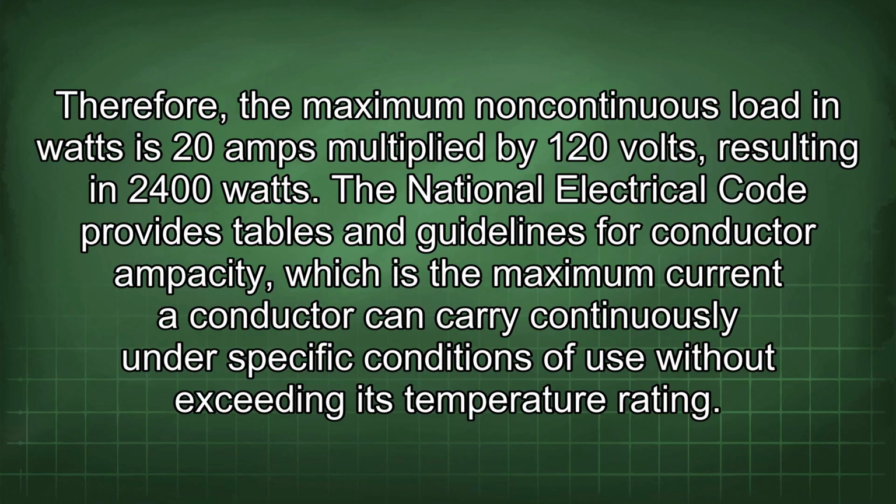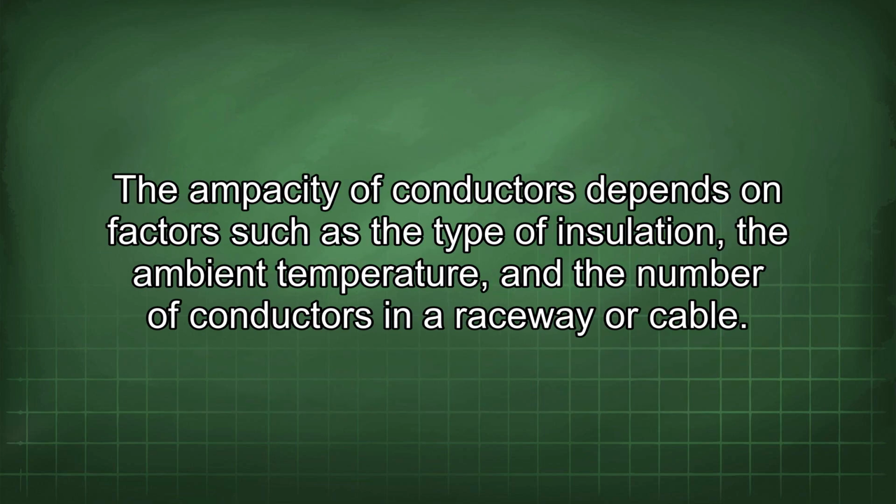The National Electrical Code provides tables and guidelines for conductor ampacity, which is the maximum current a conductor can carry continuously under specific conditions of use without exceeding its temperature rating. The ampacity of conductors depends on factors such as the type of insulation, the ambient temperature, and the number of conductors in a raceway or cable.